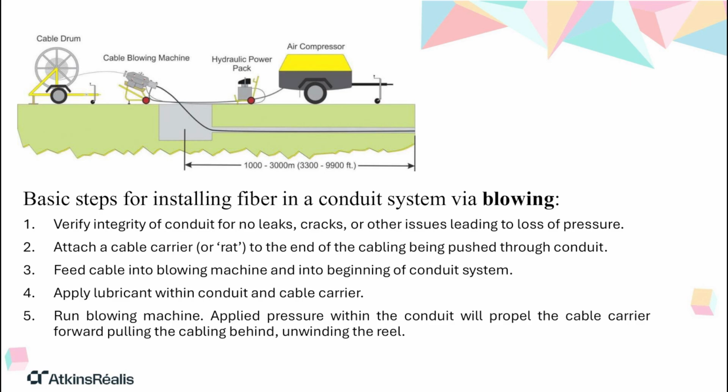And slack loops. I hear about needing extra cable. Yes. That's crucial for future repairs or modifications. FDOT typically requires about 50 feet of slack cable, coiled in each pull box. And at splice points, you need 100 feet of slack from each cable entering the splice. So for a backbone to drop splice, that's 100 feet from the backbone, 100 feet from the continuing backbone, and 100 feet from the drop, 300 feet total coiled nearby.